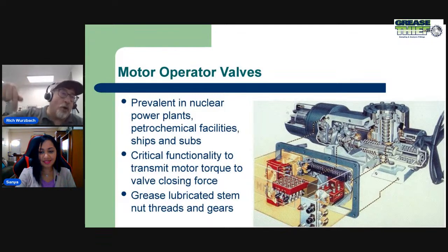It's going to go into overcoming that coefficient of friction. So it really is important that these stem and stem nuts are greased properly, that the grease is maintained, that we know its condition, and that we have some opportunity to add lubricant when it is necessary.